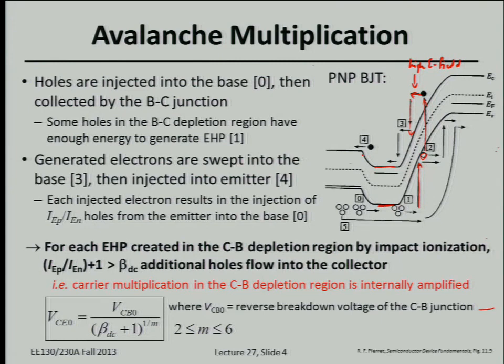The ratio of carrier diffusion across the junction is determined by the ideal diode equation. So step 5 is basically saying that if you have one electron diffusing into the emitter, then you must have something like 100 times more holes diffusing into the base, assuming the emitter is doped 100 times more heavily than the base. It might not be exactly 100 times, but it's on that order.